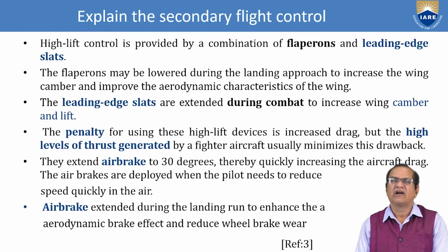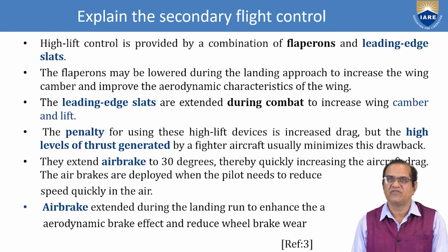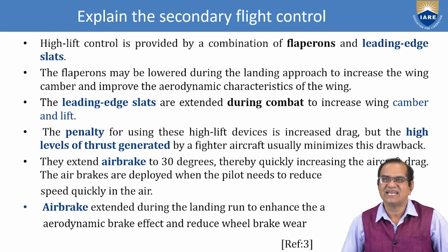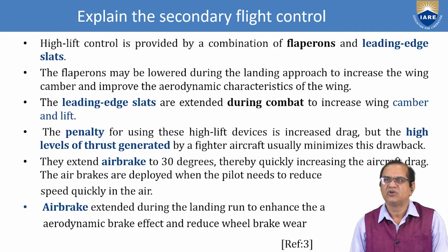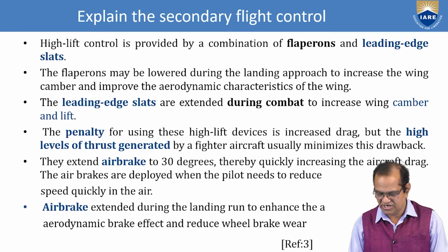So high lift control is provided by a combination of flaperon and leading edge slats. The flaperons may be lowered during the landing approach to increase the wing camber and improve the aerodynamic characteristics of the wing. The leading edge slats are extended during combat to increase wing camber and lift. The penalty for using these high lift devices is increased drag, but the high level of thrust generated by a fighter aircraft usually minimizes this drawback.